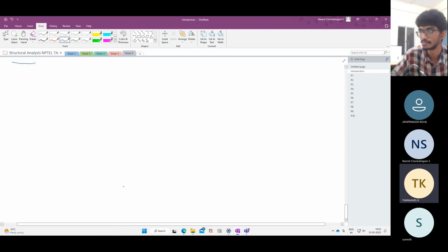Okay. So what you're saying is, if we have m members and j number of joints, the member forces are unknown. But I don't think it should be m minus 3j. It should probably be 3m, because every member has an axial force, shear force, and a bending moment. And the number of joint equations will be, as you said, 3j. So 3m minus 3j, that is fine.